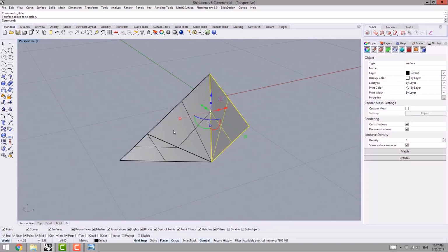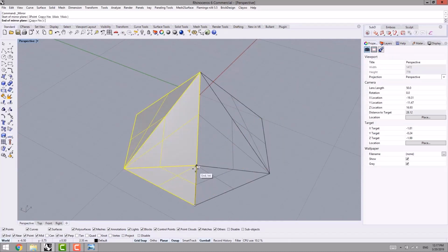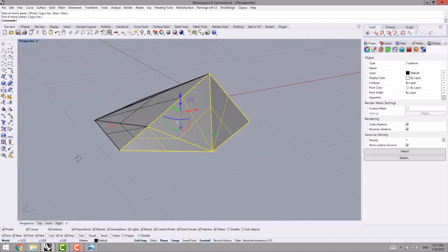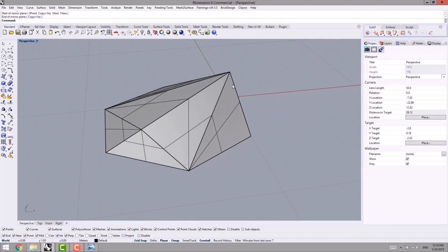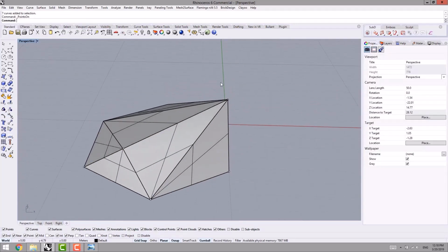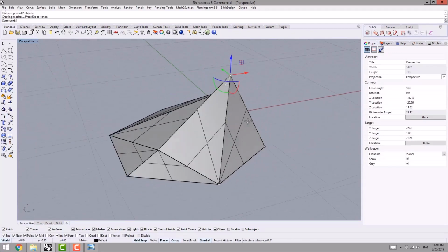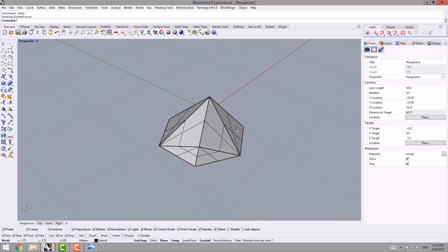I hide the other lines or the other curves, and then I select the created surfaces by using the mirror tool. I mirror them at the other side this way. And since I have enabled record history, right now I can select my control points and then modify the surface. As you can see, by moving the control points, we can apply the changes on the surface this way.